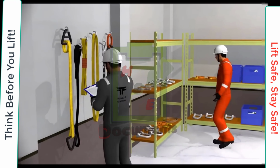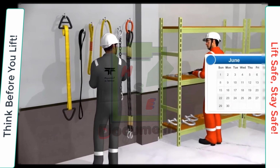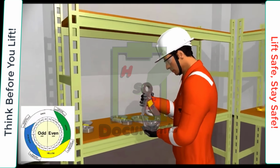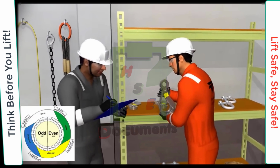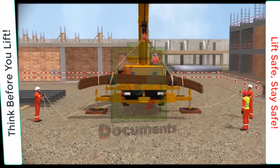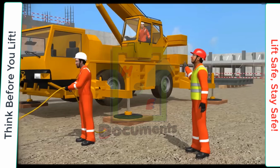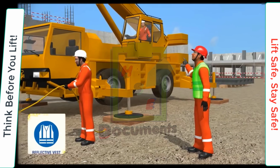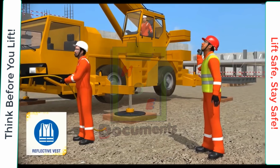All the lifting equipment should be checked by a lifting equipment controller every month, and it shall be inspected and color-coded as per the current month's color-coding practice. Every lifting work to be carried out should be pre-planned and shall be conducted under the careful supervision by a competent person. The personnel responsible for giving signals, banksmen, should wear reflective vest for allowing their identification.